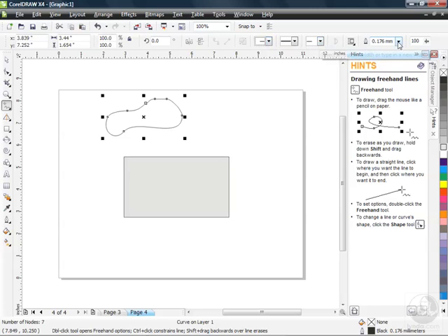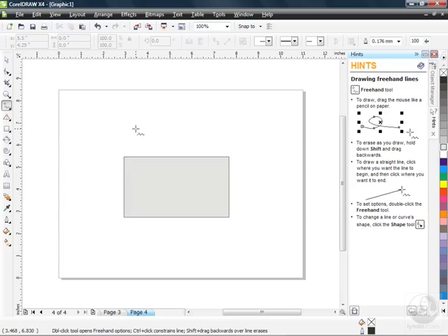But you can also select a thickness. I'm going to just make that a little bit thicker. I'm going to go up to 2. And over here where you see 100, that's our freehand smoothing. If you click and hold this down, you'll see the sliders all the way to the right at 100, indicating full smoothing is turned on. If you prefer that jagged look, you can move it all the way to 0. Somewhere in between will give you a different level of smoothing, but 100 is good right at the top. With that still selected, hit your delete key to remove it.